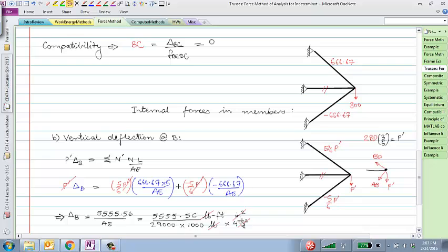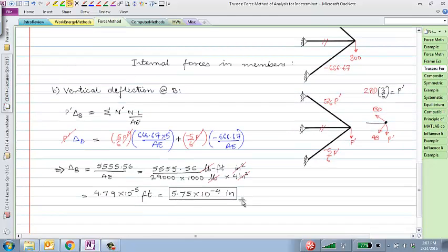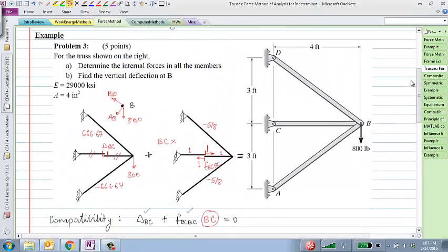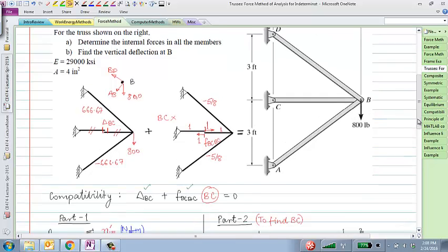And if you follow through with the calculation, you should see that what we have is the displacement at that point, just using the virtual work method. So in general, for problems with the force method, even if the structure is indeterminate, the most important thing to find first of all is the redundant forces. Once you've done that, calculating the displacement at the point of application of the load is not too much extra work.